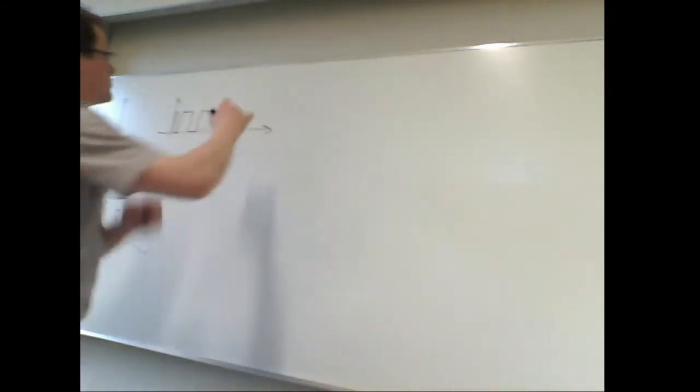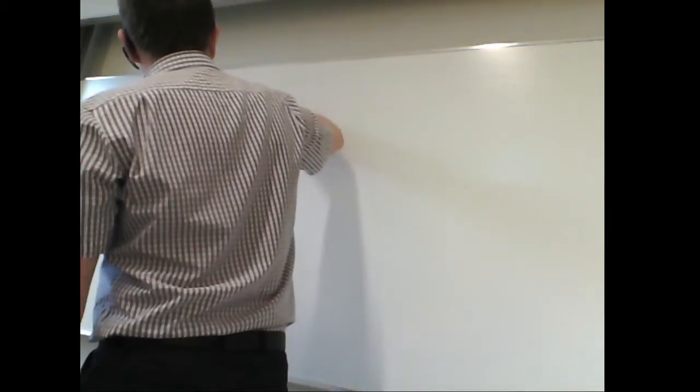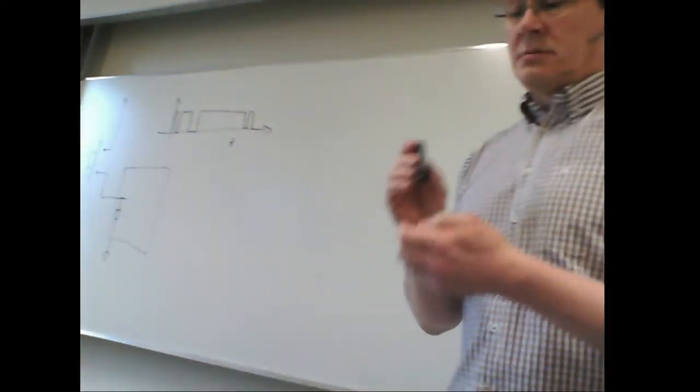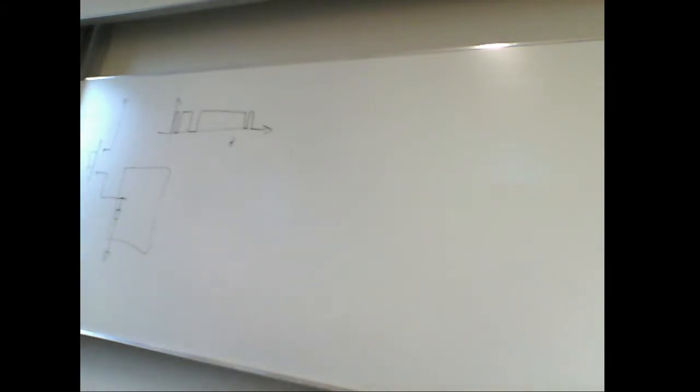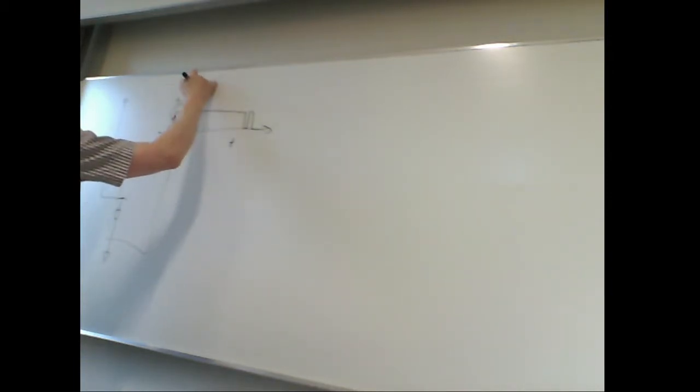The same thing when you release it. It doesn't release immediately, but this kind of thing usually happens on the other edge too. So you can get rid of these when you have an interrupt happening, for example, on a rising edge interrupt.